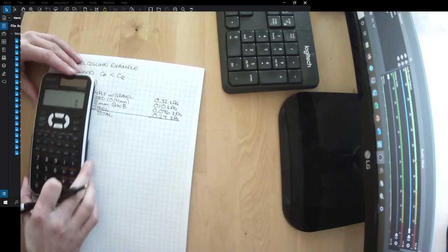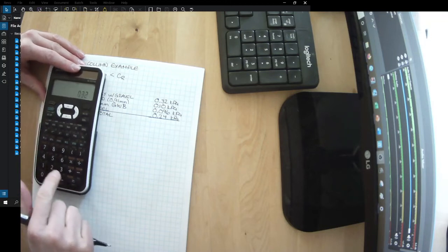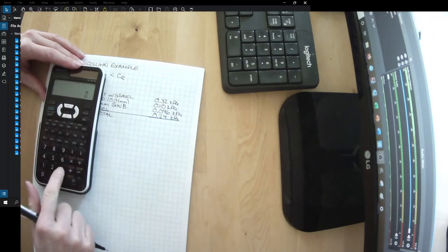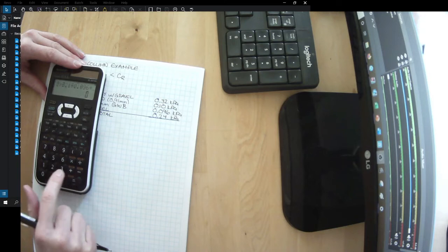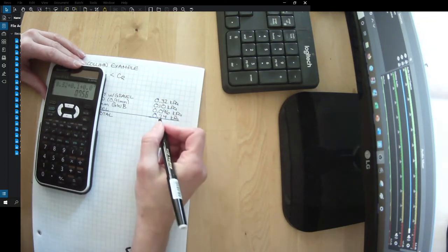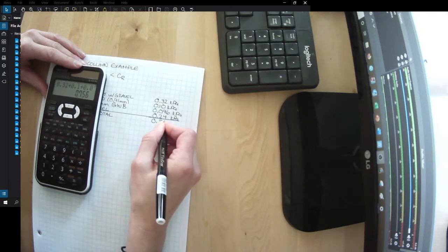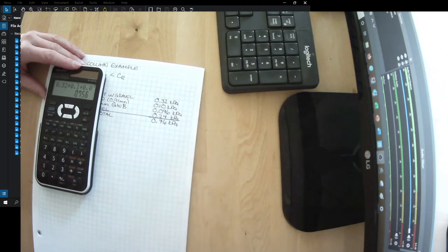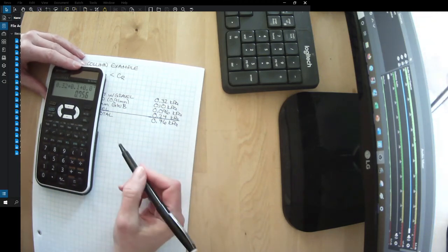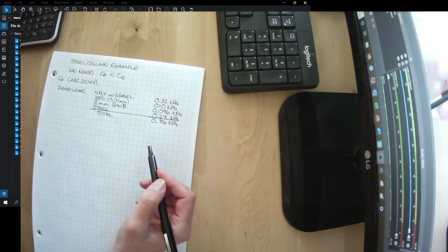We can add up the total weight of our roof assembly. So 0.32 plus 0.1 plus 0.096 plus 0.24, we have a roof assembly of 0.76 kPa. So I rounded just a little bit there. If you work it out, it's 0.756, but I rounded it up.